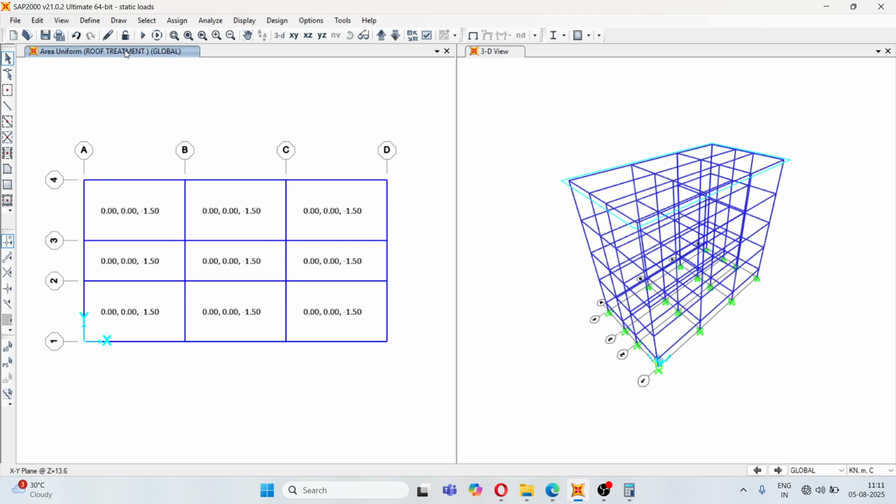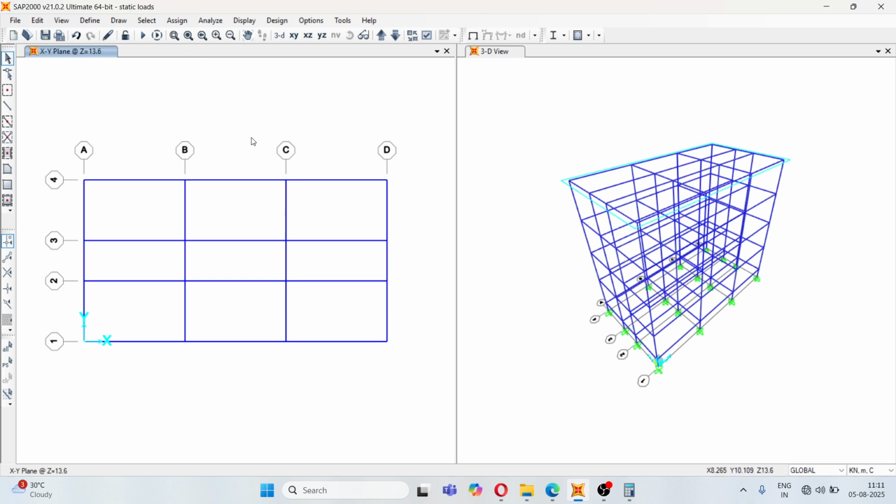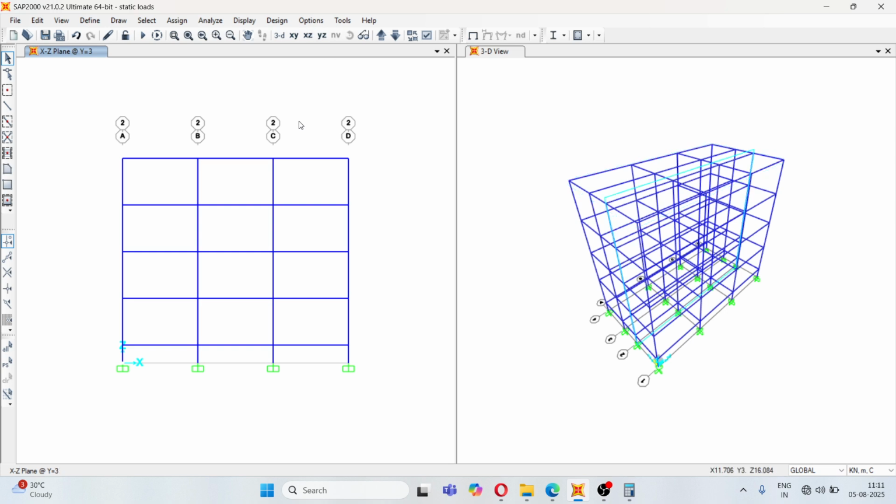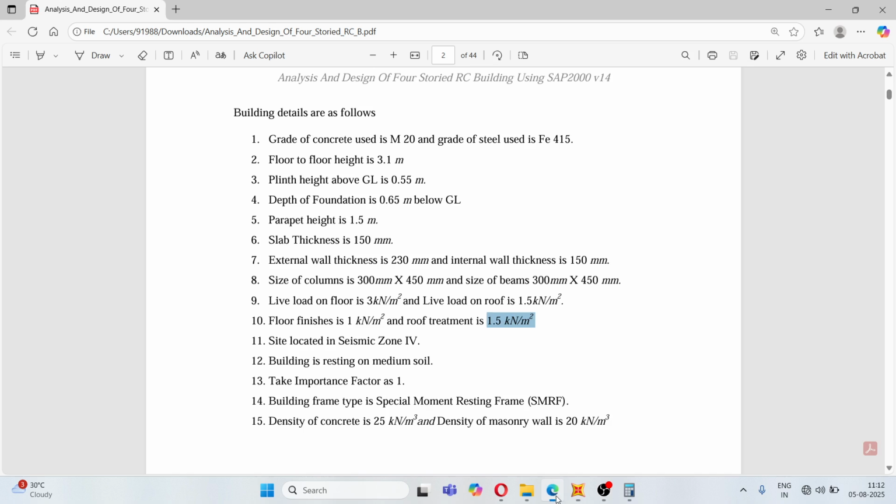Okay, now we will assign the brickwork or brick load. So we'll go to elevation mode, so you can see now. Using this arrow we'll go to the exterior frame, because we want to apply the load at the exterior. First we have to select all the beams at the exterior side, on which we will apply the brickwork load of exterior brick.